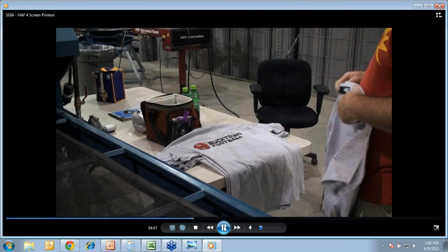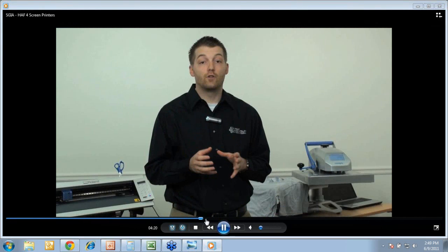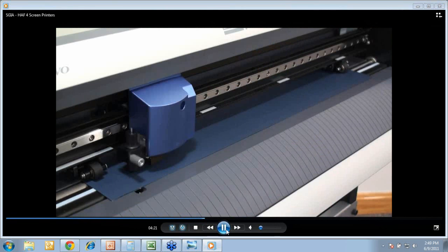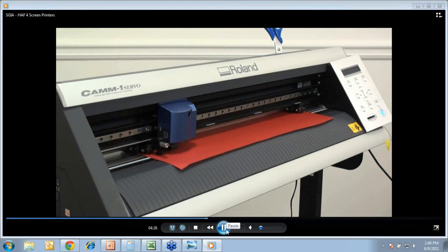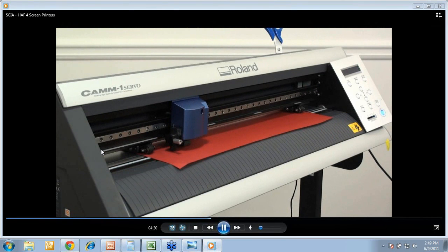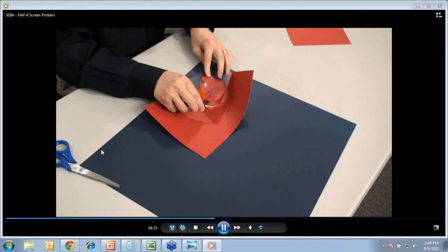And now we're going to do the same particular job with heat applied film in the process. And for those of you that don't have a cutter, you cut it and weed it. So here I'm going to cut all my designs out of thermofilm. Premium Plus would be the same. It can be layered with thermofilm as well and other polyurethane-based materials.